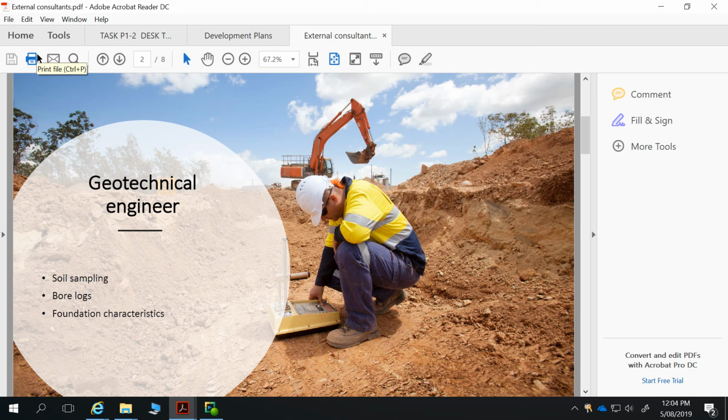Sometimes we're building on a place that has none of that horizon A and very little of the horizon B, but then that's going across this bit like this, we're cutting into the soil. We might have far more reactivity at one corner than we do at the other corner. That's actually a bigger problem than if we had uniform reactivity across the whole slab, because slab cracking, building cracking, it's about differential movement. It's not only about total movement.